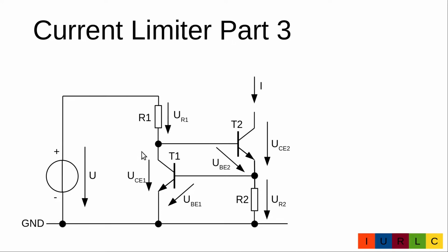To solve the problem, we introduce a second transistor with a low current through it, and this current is also not too much varying, so that we have a low and more or less equal power at this transistor. This causes a stable base emitter voltage on this transistor, and with the stable voltage we measure the voltage on the current sense resistor. The circuit works as follows.